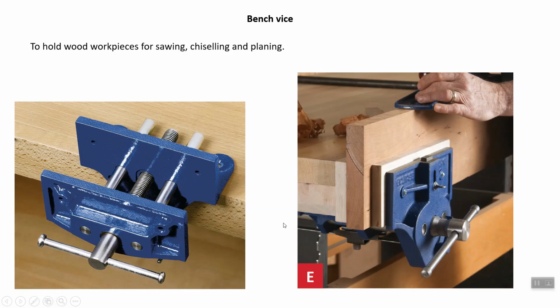As you can see, the bench vise is fixed onto the workbench, and then you use a scrap material between the jaws and the material itself, so as not to damage the material when you squeeze the workpiece in the workbench. Then you can plane easily without damaging your work. So this is an important tool for woodworking.